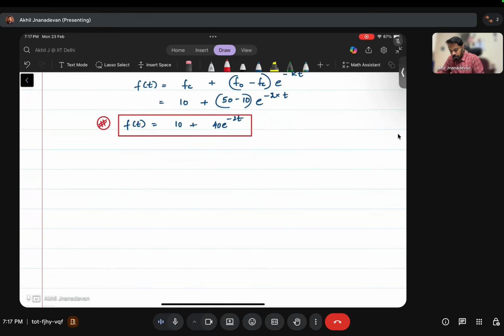If we want the cumulative infiltration at any time, capital F of t is the integral from 0 to the time we want of f of t dt. Here it will be 0 to 2, since we need infiltration after 2 hours.